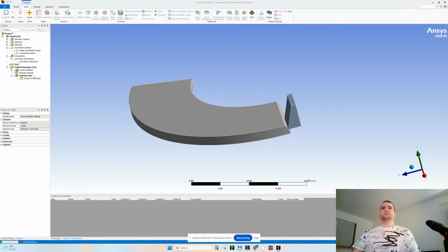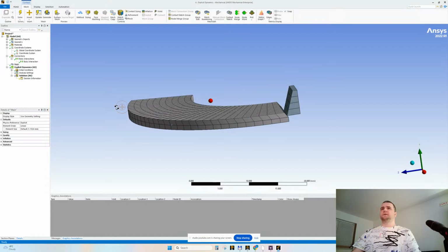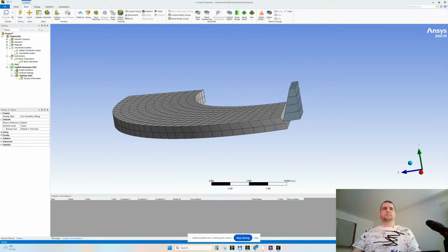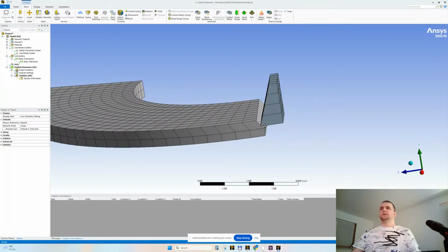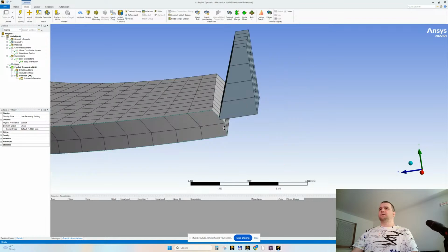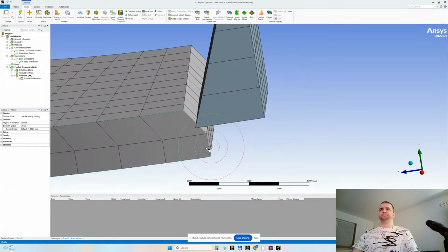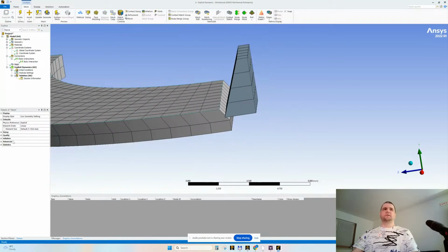Right-click generate mesh. Let's see how it looks. It looks very coarse, to say the least. So what we're looking at now, we're zooming the ruler in order to get a glimpse of the characteristic sizes, let's say. So 1, 0.5 or something. Here on the element size, I can write maybe 0.5, all right?